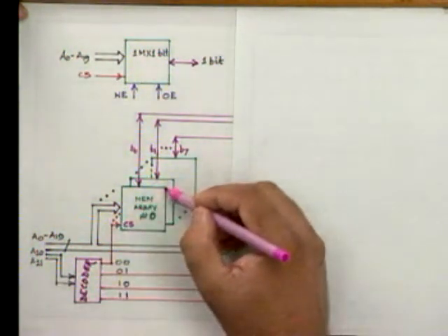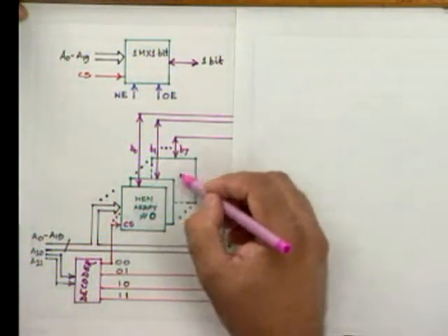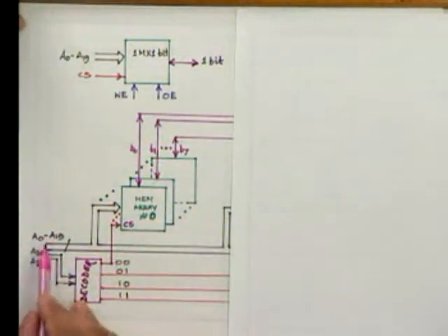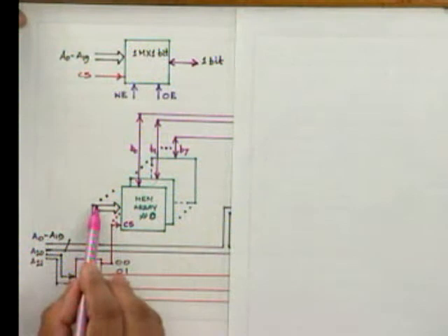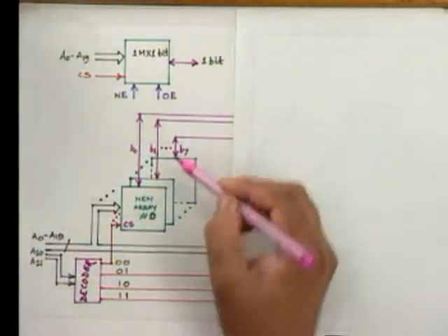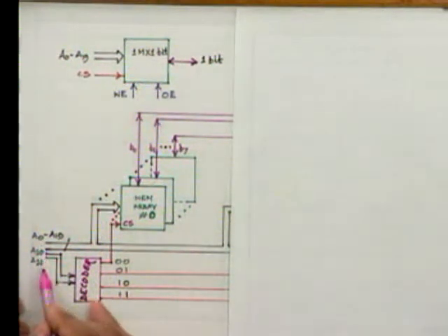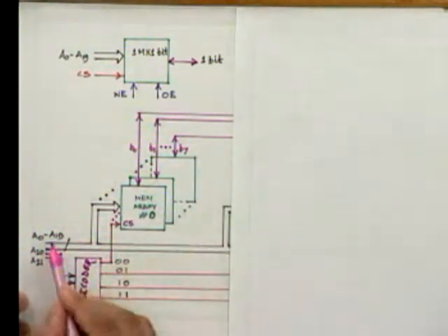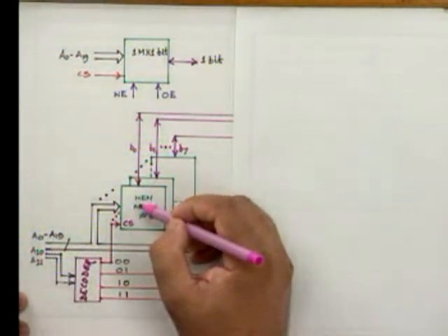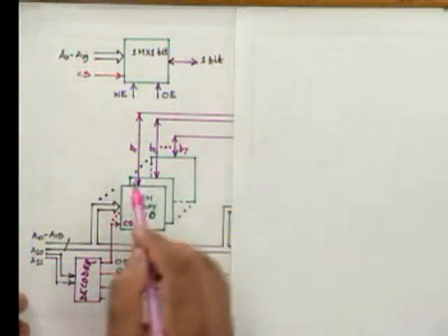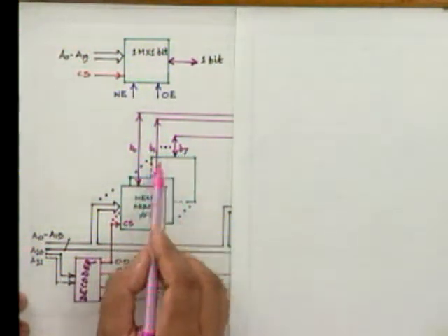chip select. That means if it is 0, 0, then this chip is selected. And when this is selected, you see all the planes, that means all the chips in this stack, are all selected, right? This chip select line goes to all the chips in this stack. The other address lines from A0 to A19 are also fed in parallel to each of these planes, right? Each of these chips. This goes here as well as here as well as here, which means for a particular 22-bit address, depending upon A20, A21, if it is 0, 0, then the entire stack here is selected, and depending upon A0 to A19, one cell and the corresponding cell of each of these planes, that means each of these chips, is selected, therefore making B0, B1 and B7 lines